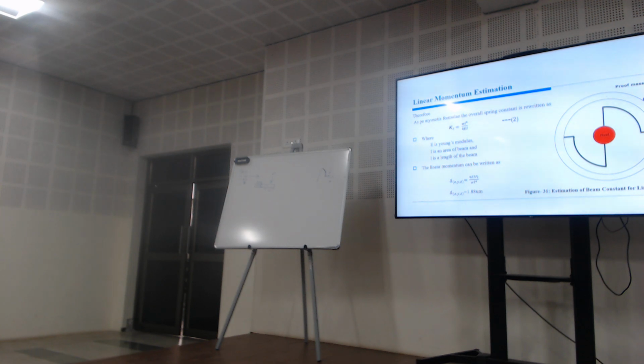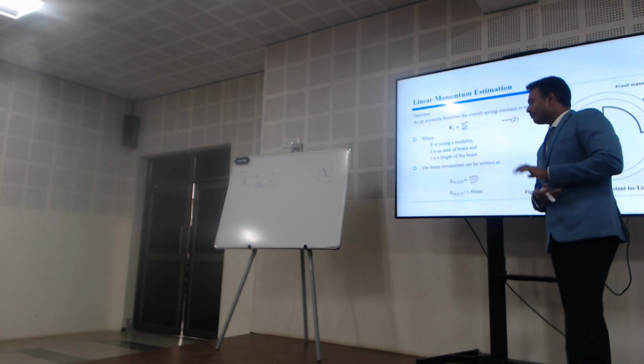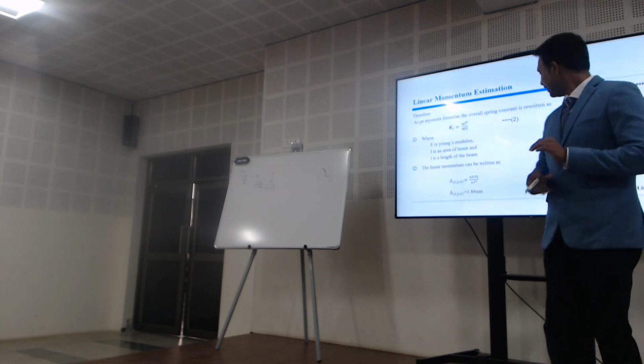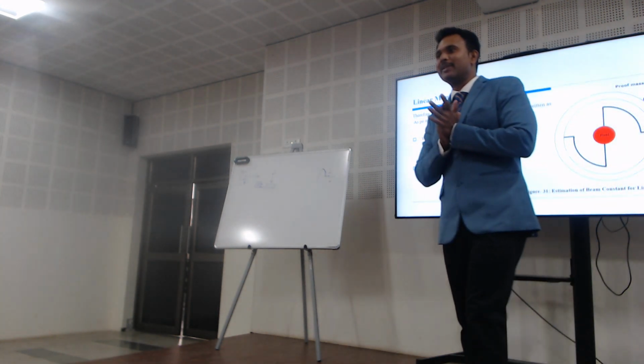Those formulas go into our K value. Now what is my K value? 2K. So now I am giving that 2K over here. Now finally I get how much displacement is coming for this structure. So that displacement is 1.88 micrometers, in either the x, y or z direction.